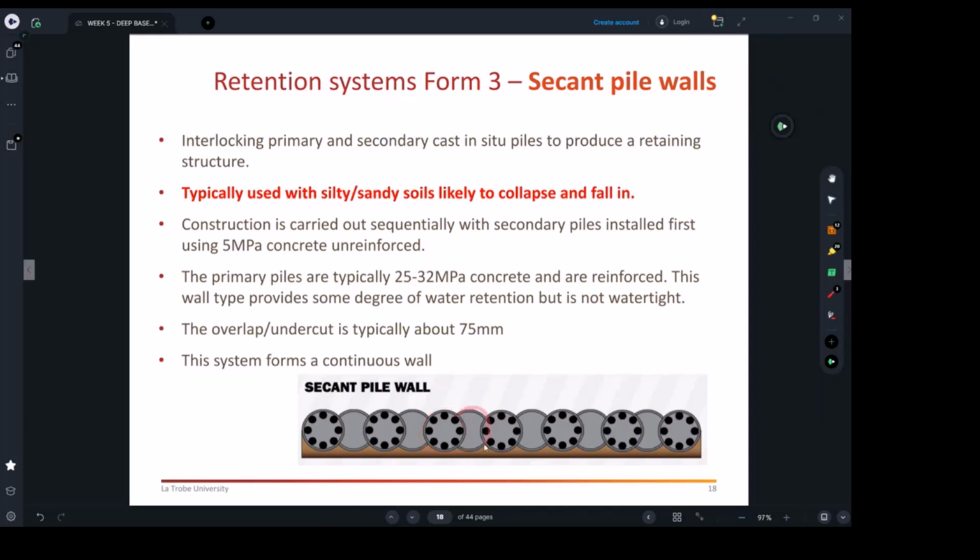But for building those ones, one of the methods is they build the unreinforced sections, the ones in between, first. So they build these ones first, right? And they do it before they actually get hard, while it's still kind of excavatable. So they build this one first and this one first, and they just pour mass concrete. Then before it gets hard, you need to be careful with the timing of excavation.